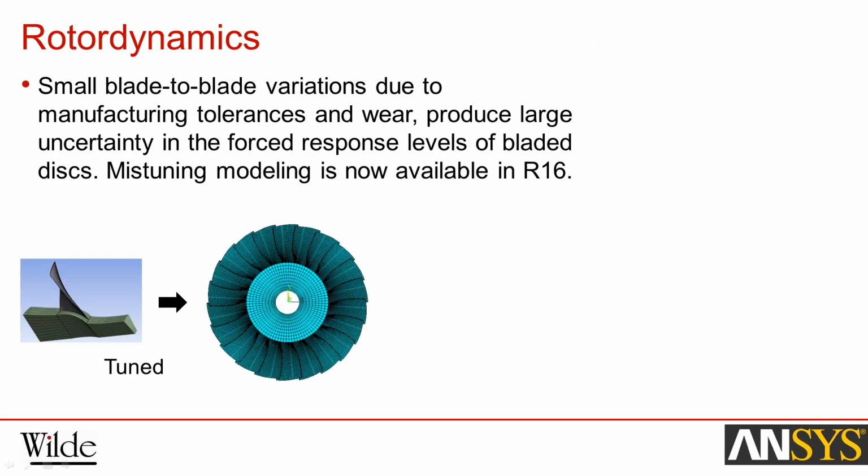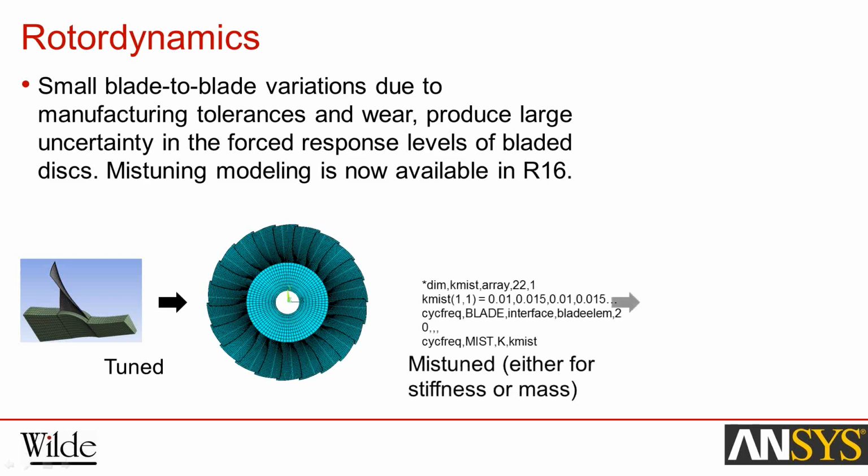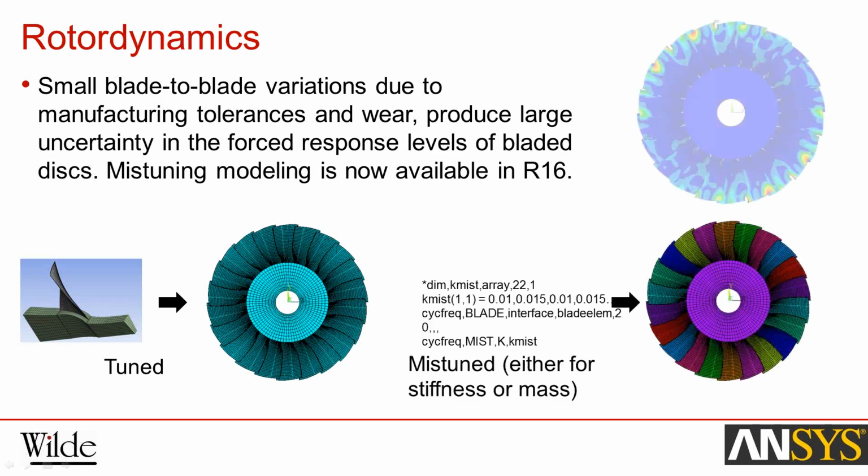Small blade-to-blade variations due to manufacturing tolerances and wear produce large uncertainty in the force response levels of bladed discs. This is now modelled in version 16 using the mistuning model.